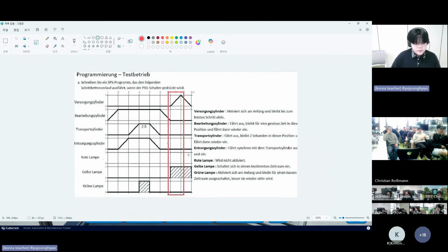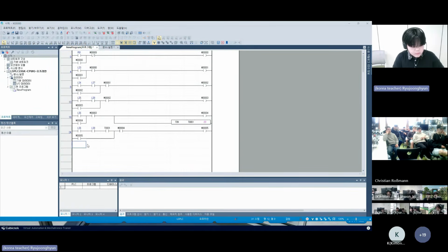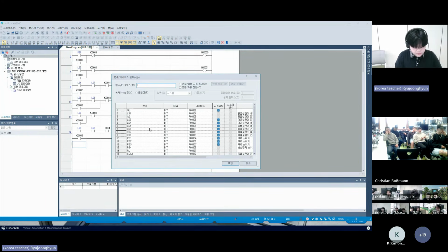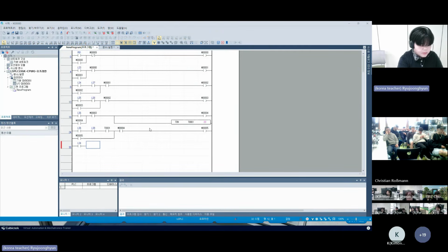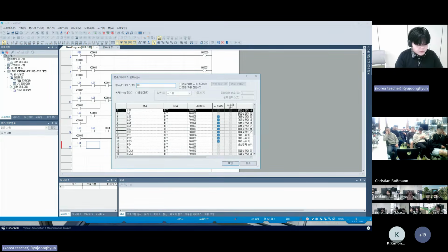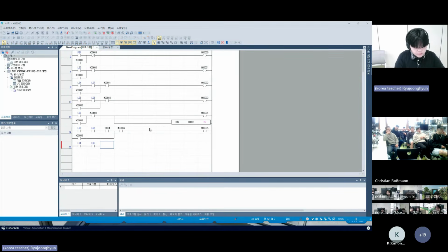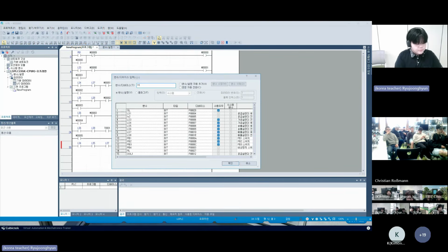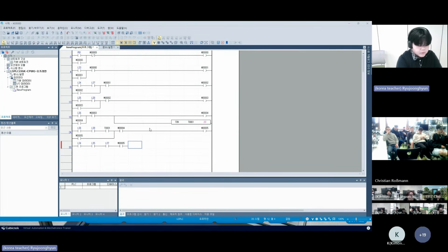Now let's move on to the circuit and explain the white line. The previous step works up to M5. First write limit switch S4 as an A contact, and then write S5 and S7 also as A contacts. M5 is the previous step, so write M5 within the circuit.